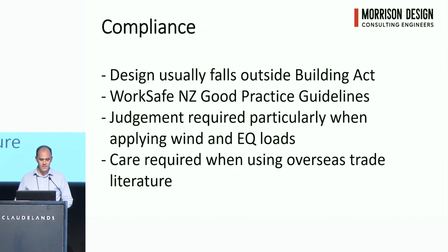In terms of compliance, the design of scaffolds usually falls outside the Building Act. Sometimes it comes inside, but it's usually outside. So WorkSafe New Zealand has a good practice guideline, and that provides information on loads we should be applying in terms of gravity and live loads. But it doesn't cover wind loads or earthquake. So for those loads, we need to be looking at 1170. And it's worth noting that 1170 is intended for buildings. So right from the outset, we're getting a standard that's not really intended for scaffolds, and we're applying that standard to scaffolds. So we certainly need to be using care and judgment with that.